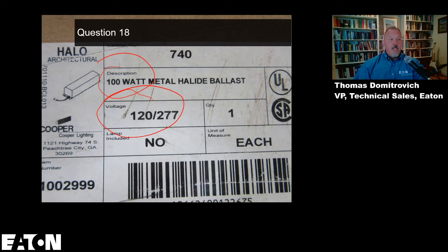It's like buying a 600 volt rated overcurrent device as opposed to individual devices that are rated 120, 240, 480, etc. If you just bought it 600 volt rated, then you can apply it in many more locations than just a 120 volt straight-rated device. So you would rely on the manufacturer's specifications and catalogs as you're picking the lighting fixture or the luminaire.